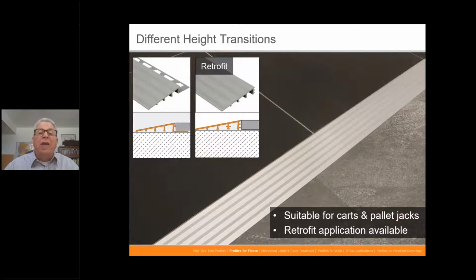It comes with and without the anchoring leg to fit it under the tile. We would always prefer it go down in conjunction with the tile installation, and the anchoring leg is fit underneath the tile, the first course of tile. But if you don't, then this one is a retrofit that can be used.